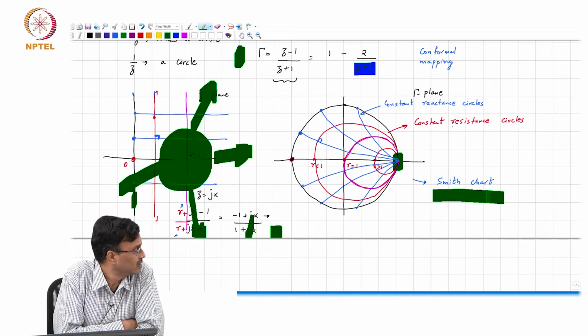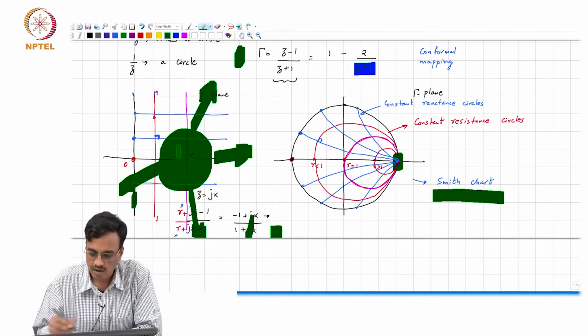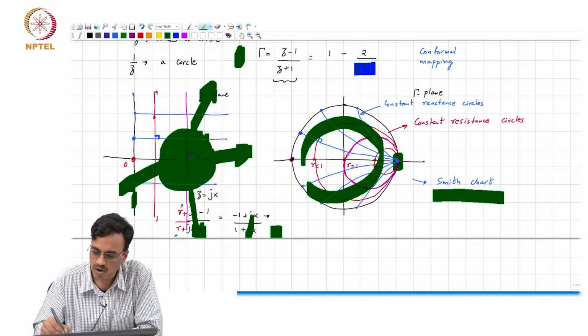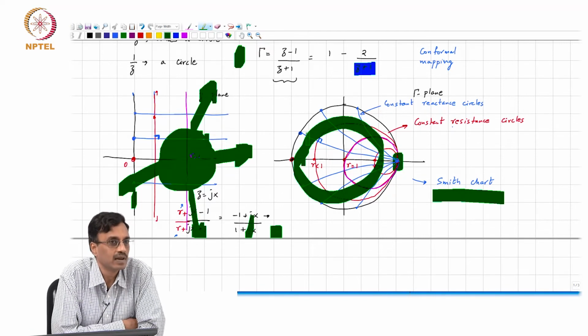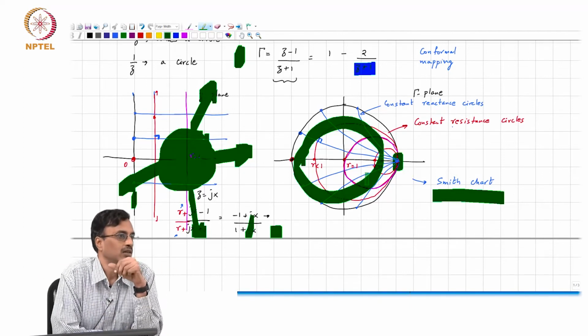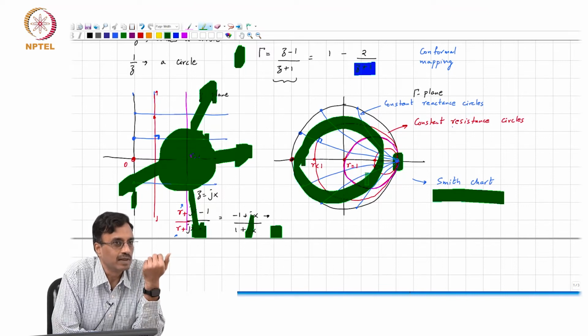If you had a chart which plotted the reflection coefficient plane rather than the impedance plane itself, then the critical area here would translate to a large part of that picture. So you dedicate a large portion of that area to, within quotes, the information bearing part of the z plane, and all the periphery is reserved for, within quotes, unimportant parts of the z plane.